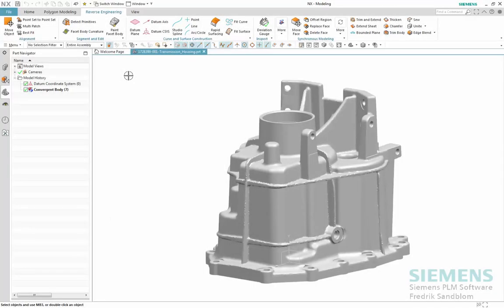Reviewing the scan data, we realize that the actual axle outlet and bearing seating area needs to be rebuilt in order to obtain maximum accuracy and also to have the correct relationships with all the other axles and gears that the specific axle interacts with. The idea here is to use material deposition or additive manufacturing to fill the entire axle seating and machine it back to its more precise definition. This will be done by creating surfaces for each feature in the axle seating area.